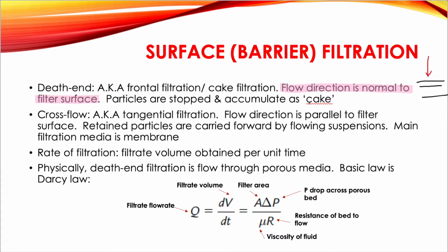What happens is the particles will be retained on the surface of the filter media. The particles are stored and accumulated as cake. Whereas cross flow is a tangential filtration. The flow direction is parallel to the filter surface, and the particles are carried forward by the flowing suspension because the flow is parallel to the surface of the filter.